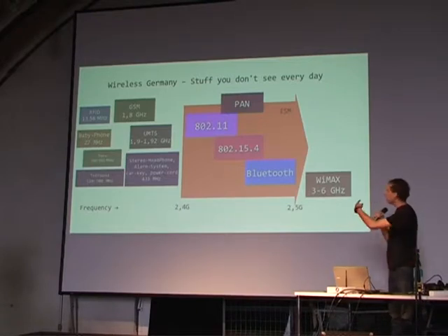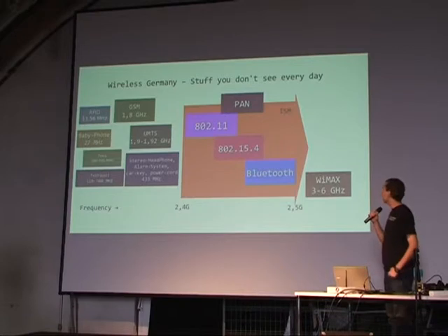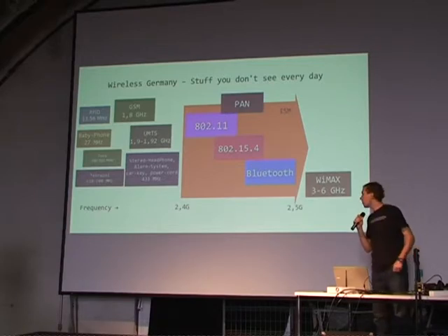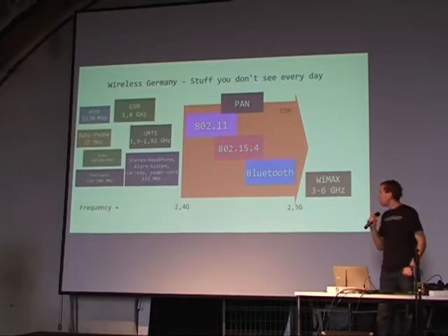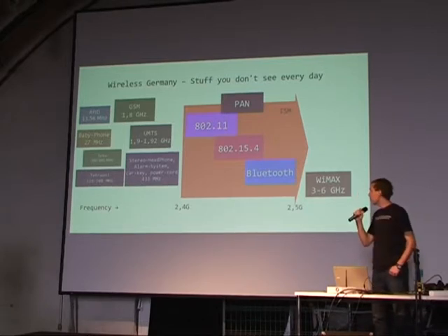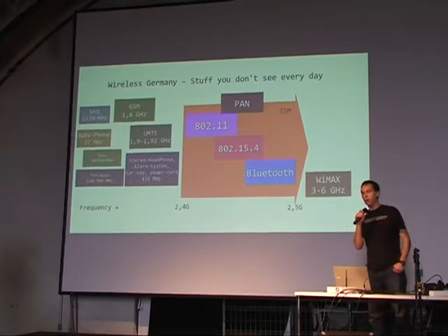And wireless LAN covers, I think, the whole ISM band in some standards. Other stuff that is not necessarily ISM band is mentioned there, such as RFID or GSM, UMTS stuff, or your favorite stereo headphones, which practically can all be received with a USRP if you have the adequate hardware or the adequate daughter board.